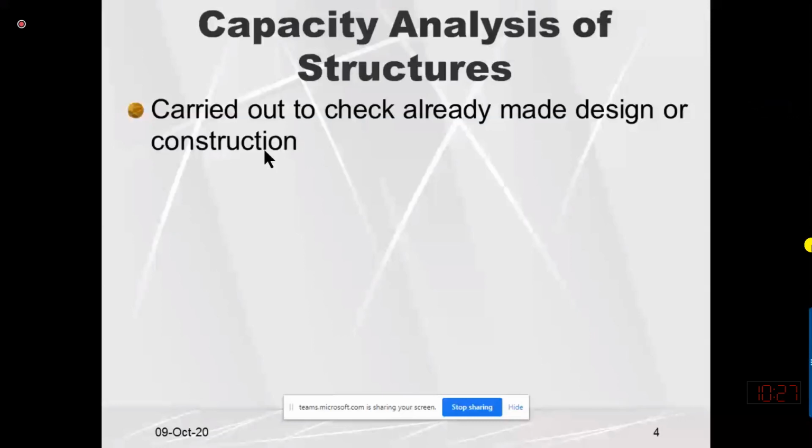So the moment that I have computed from the equation is the moment carrying capacity. I will compare that moment carrying capacity against the maximum moment which is produced along the beam from the bending moment diagram. If moment carrying capacity is more than applied bending moment, beam is safe to use. If it is less, then structure is not having sufficient strength.